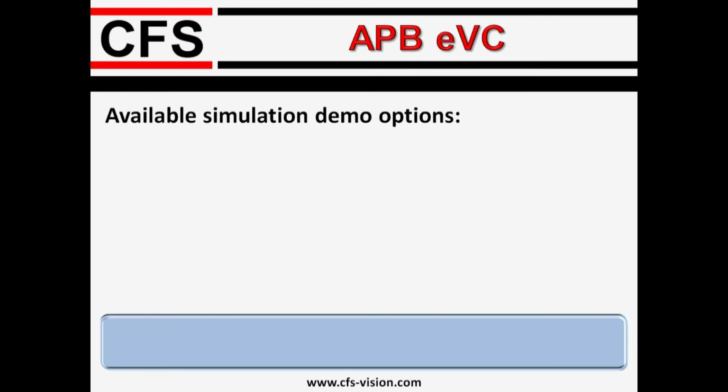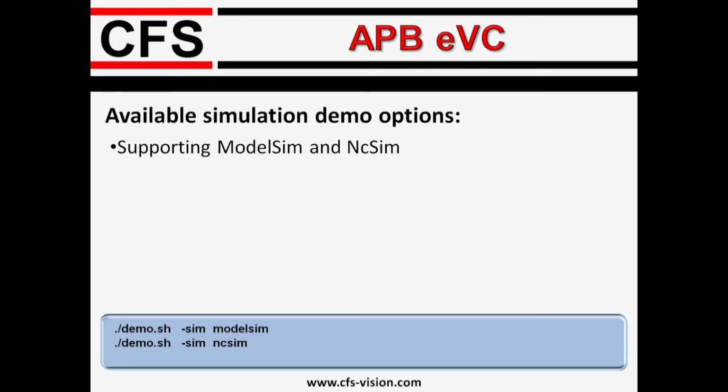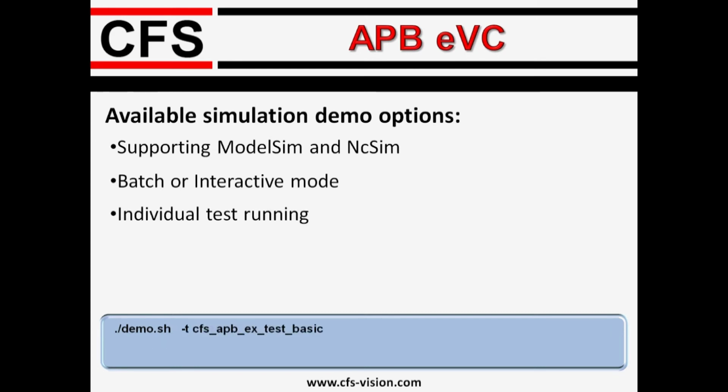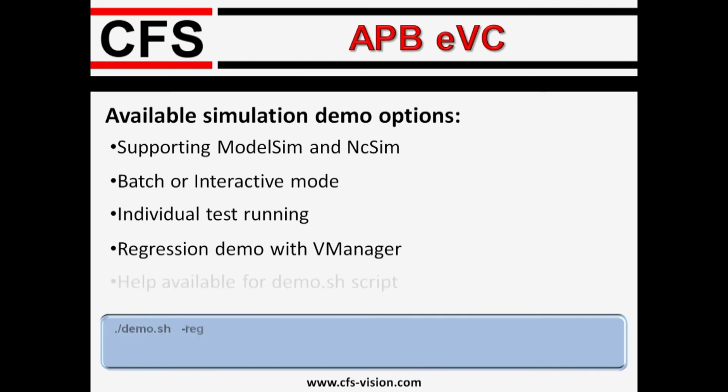The demo simulation script supports running simulations in both ModelSim and NCSim simulators. The simulation can be invoked in batch or in interactive mode. There is also the possibility for running individual tests or running regressions using vManager. All the available options for demo scripts are available from Help option.